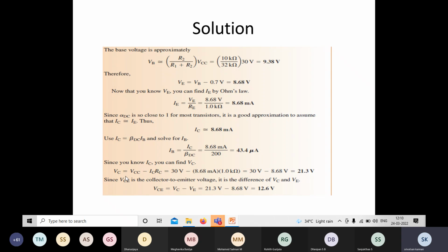The input junction is forward biased, the output junction is reverse biased, right? So for the positive cycle of the input, IC will increase in the positive direction or increase in the reverse direction. Let us assume that the input signal is a sine wave. So for the positive cycle, will IC increase or decrease?